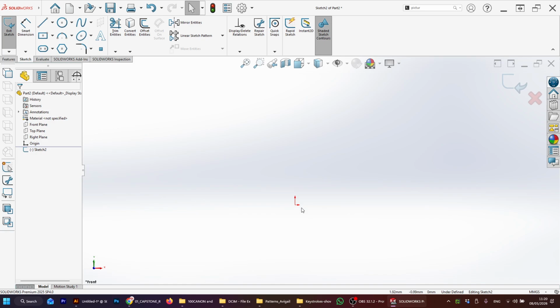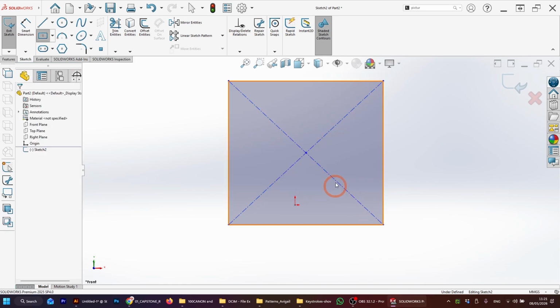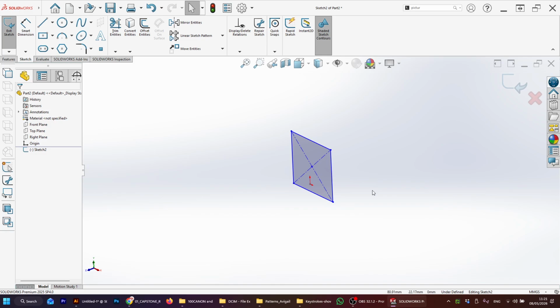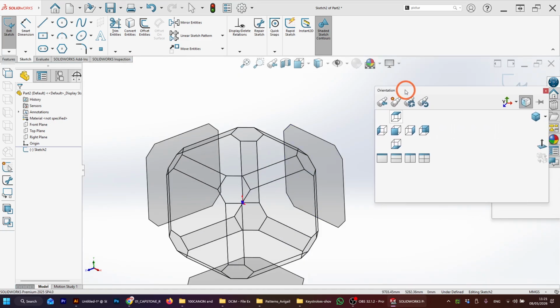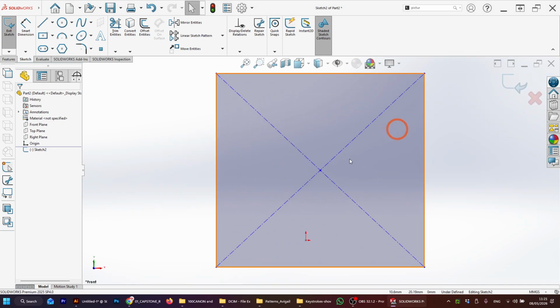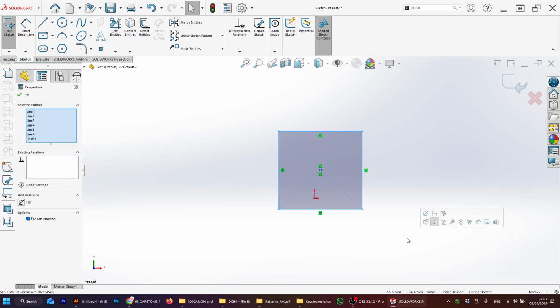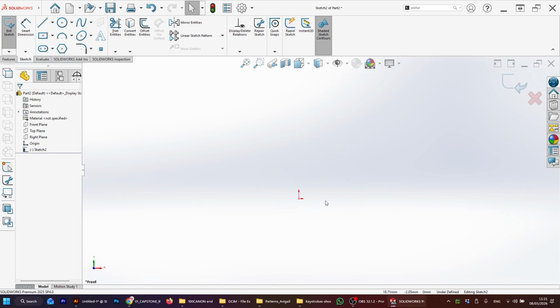So now I opened it. If I want to be sure that my sketch didn't turn, I will show you that later. If, for example, this happened to you, and by mistake it looked like what happened to my sketch, everything is off, push space on the keyboard and click on the center cube. That's gonna bring it perfectly front to you. Okay. Now, I did that.